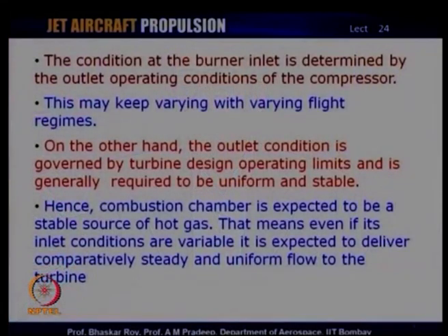Now, this stable source of hot gas is necessary to be delivered under all operating conditions, especially when the aircraft and the engine is accelerating or decelerating, and this requires that the combustion is always held and it is never allowed to be extinguished, or what is known as blown out, under all kinds of operating conditions. And we shall see that there are certain parameters which are to be held very strictly within certain specified limits, and those parameters are what we are going to discuss in a few minutes from now.